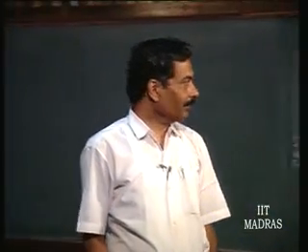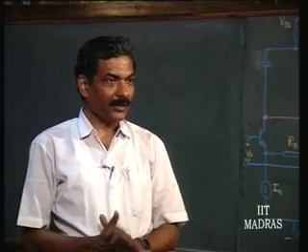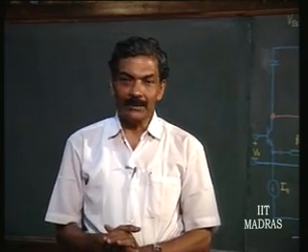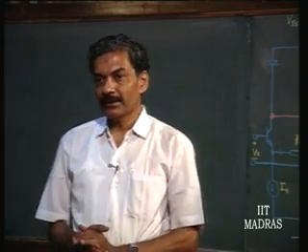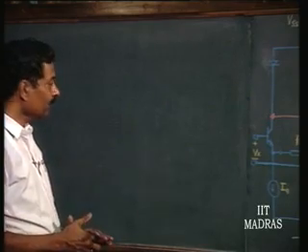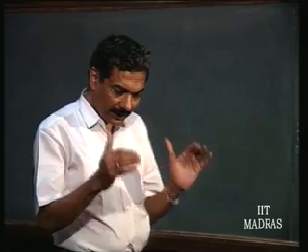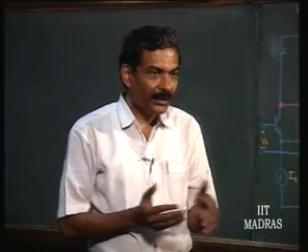So, we have just now seen how the idea of log anti-log can be very neatly implemented with the help of a matched pair of transistors. This is obviously a single quadrant multiplier. In fact, we will see later how any single quadrant multiplier can be converted into 4 quadrant by simply biasing it.